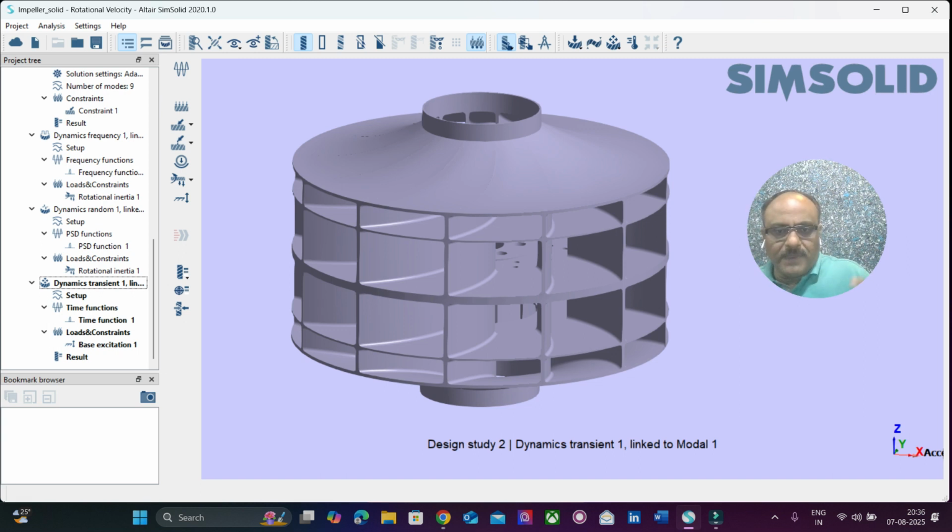So what we can do is identify the power spectral densities, the variations because of the excitations, and then we can try to simulate it in the test. So that is the basic reason we say a test model and a finite element model, or a virtual simulation model, the digital simulation model, are compared to one another, correlated and then updated.